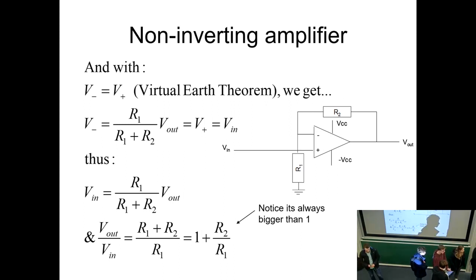The graph that drops off. Yeah, the graph drops off. Exactly. You plotted that. And the big graph that you've got is the operating envelope of the op amp. When you apply feedback, you operate in that space. And then you've got a flat line of constant gain all the way across until it hits the descending line, and then it can't work anymore and it falls away. Runs into practical problems. And that's where virtual earth theorem doesn't apply anymore, once you've hit that line.